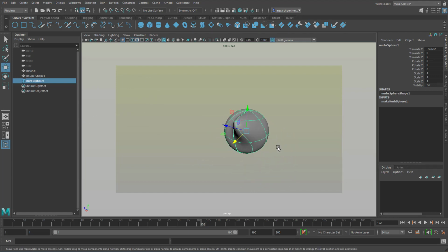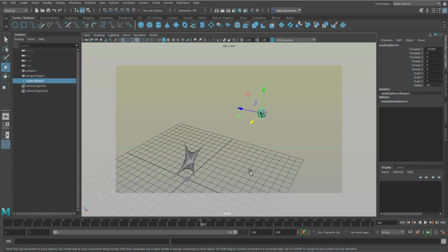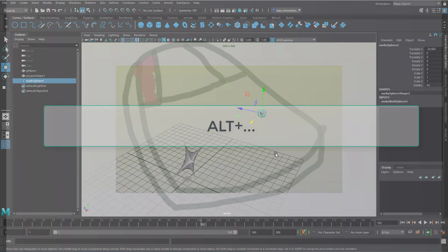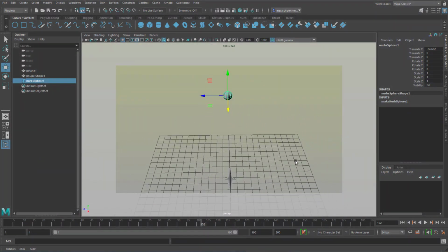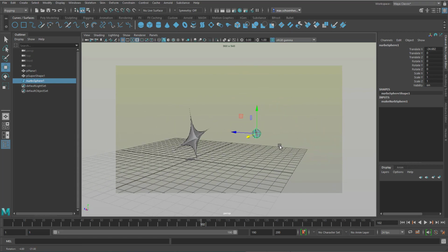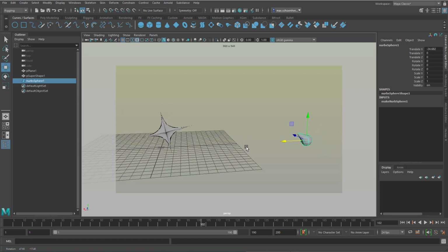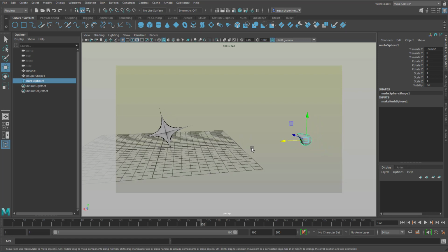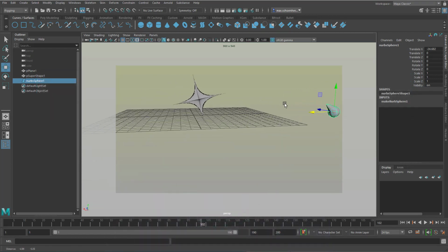If you want to see all objects, you press the key A, and when you do the rotation thing with the Alt and left mouse button, now you rotate around basically every object in the scene. If you have 1000 objects in the scene, you rotate around the center of all these objects. If you press the middle mouse key with the Alt key together, you do this.